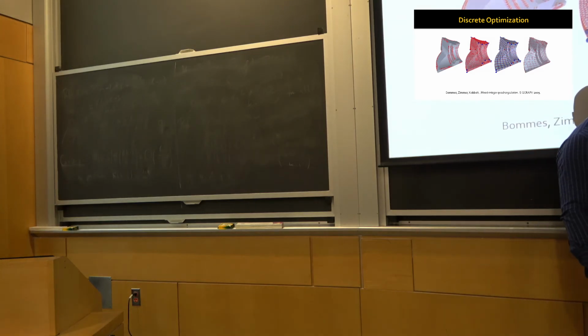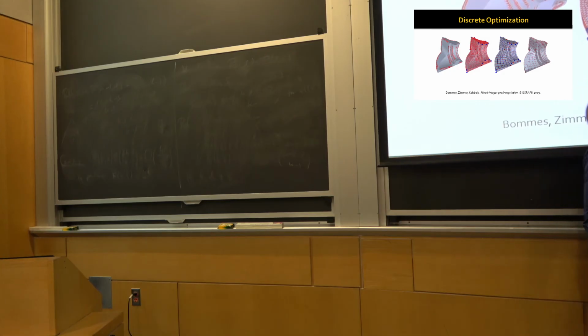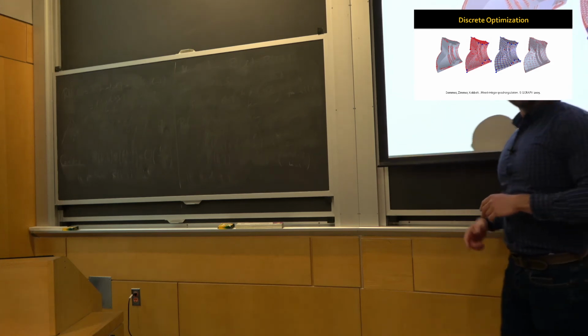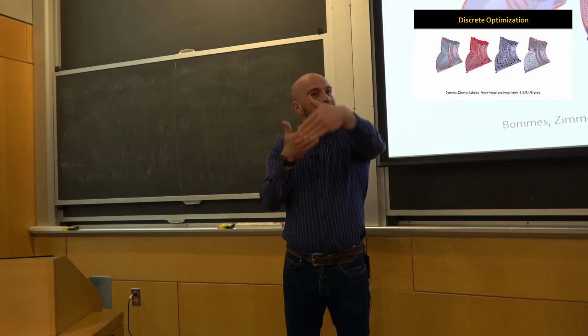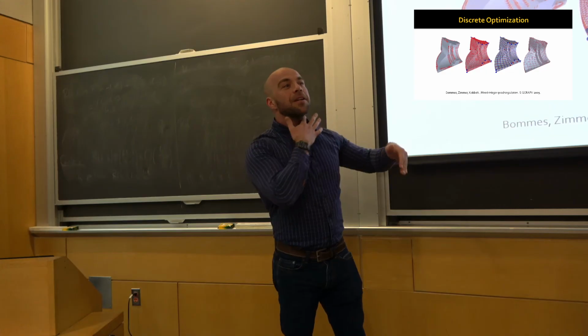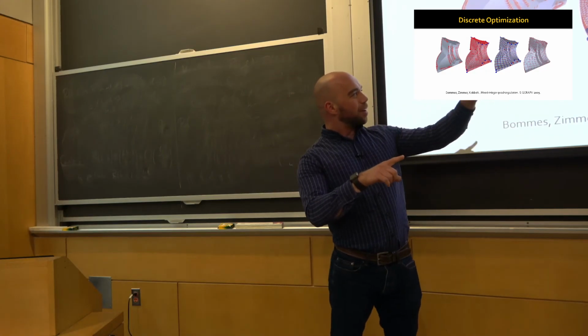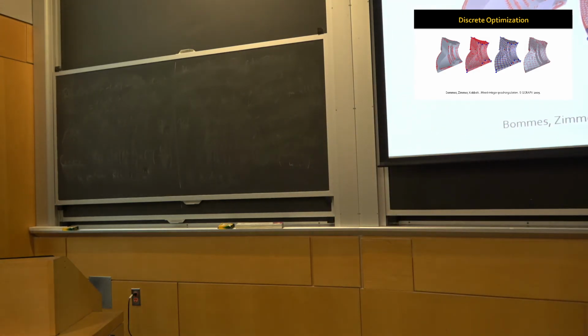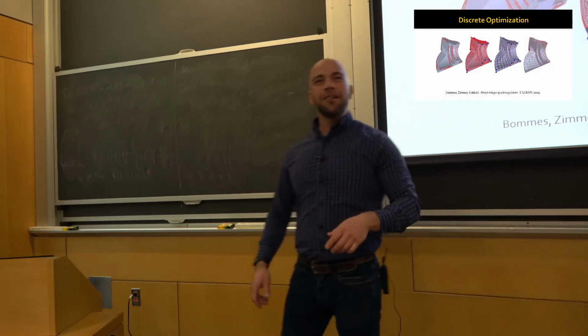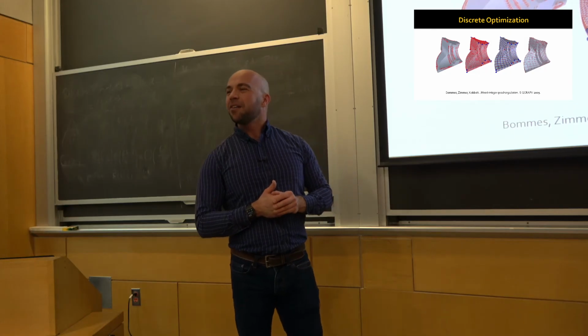But in any event, with the fan disk, one of the things that we like to do in scientific computing is quad meshing, which is exactly what you see here, right? It's covered in these little quadrilateral elements. In order to do that in a nice efficient fashion, we're going to have to minimize the distortion of all the quads. We want them to be kind of planar and have flat looking edges. But in addition to that, there's discrete structure, like how many quads do I place along a different part of the surface? And where do I place singularities, like this point here, which is adjacent to 1, 2, 3, 4, 5 quads instead of 4, right? There's not a regular grid there.